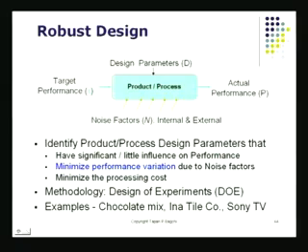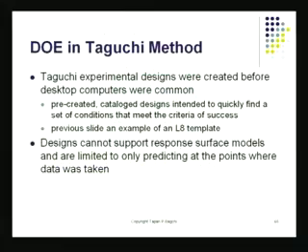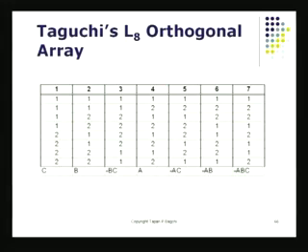Of course, when you're manipulating simultaneously many different variables, the only way to do that is using a DOE setup. And that we can, of course, see DOE is a key element in the Taguchi method. And if you look at the plans which are used, Taguchi's plans, they look a lot like the full factorial design. But something I've got to remind you of, Taguchi is not trying to use ANOVA. Taguchi does not really try to explicitly monitor or measure interaction between factor effects. Taguchi does not try to do that. He does try to figure out the interaction between noise factors and design factors. That is one thing that he tries to do.